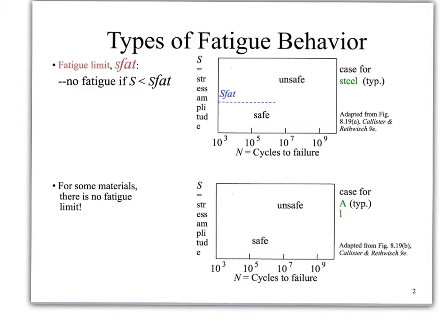This is fatigue. Our next topic will be the SN curve. The SN curve was developed through laboratory simulation tests that involved rotating and bending along a beam. Repeating this procedure multiple times gave us a variation of data points, and then this stress was plotted against the natural log of the cycles for each of the different specimens. This is taken as either the amplitude, which we just defined earlier, or the stress max. The higher the stress, the fewer cycles to failure.